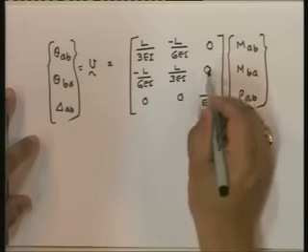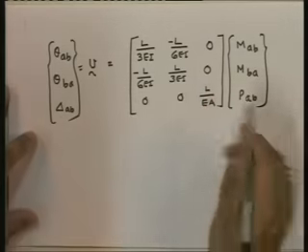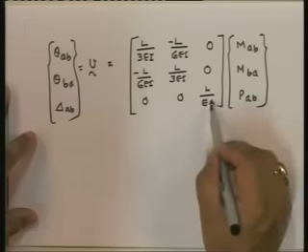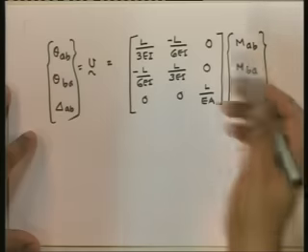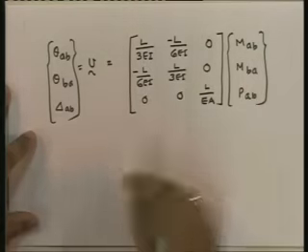That is the reason why these are zeros. Okay? And therefore delta AB is equal to PL upon EA. We already know that. Okay, and these we've already evaluated earlier. So this is all that happens. If you have a member where both flexure and axial deformations have to be included, then all you have is this term, but you will see that in a straight member, these two terms are 0. So the axial deformations are uncoupled from the flexural deformations.